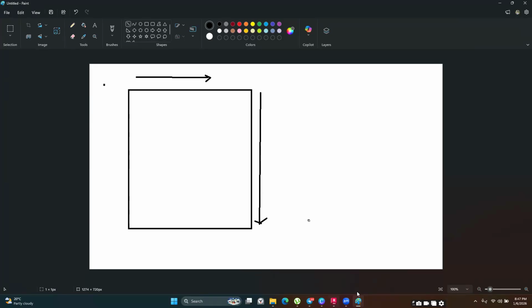So when you've done your analysis and you want to check the results for your slab, you want to have all your panels having the same local axis so that it is easier to understand. If you are displaying the moments along the X, you can see that they are going along the same direction. The danger would be at this point here.